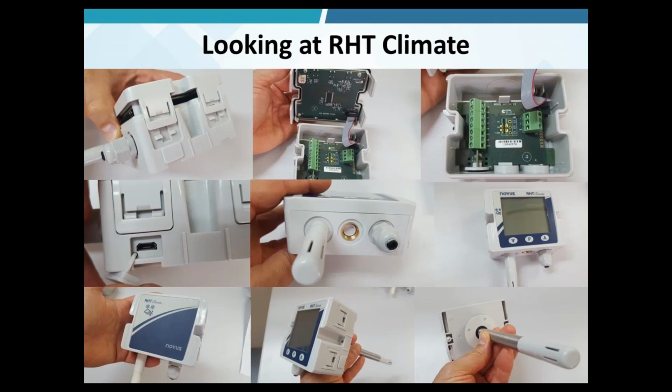All connections are performed inside the connector and pass through the cable gland. The USB port on the left is protected by a rubber cap. The RHT probe is integrated with the enclosure. It can be removed. The device has a spare for an additional cable gland in the middle of the box. The duct mount type has the probe coming out from the rear. The probe holds a flange for fixing into the duct.